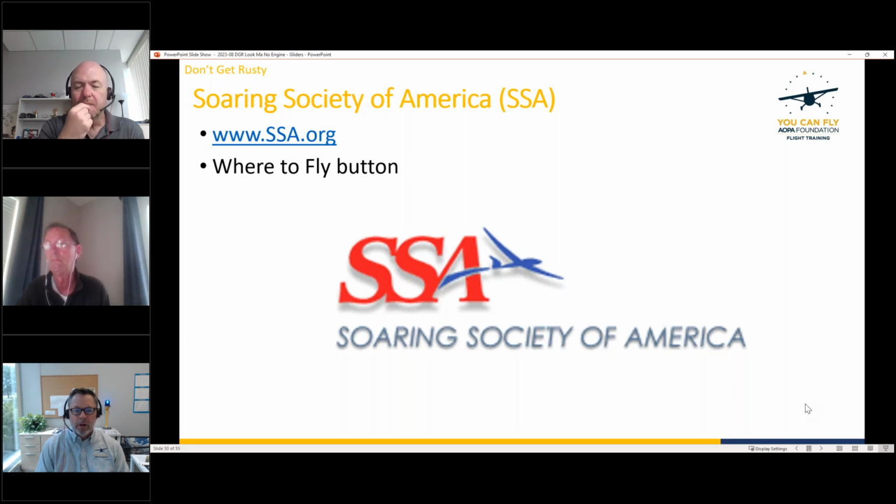Do you need a current medical to fly gliders? You do not. There's no medical required to fly a glider. With a sport airplane, you don't have to have had a medical, but you need a current driver's license, and your medical could not have been denied, suspended, or revoked. But when it comes to gliders, of course there's always 61.53, I think is what it is, the reg that says you can't fly with a medical deficiency, that for some reason you shouldn't be flying.